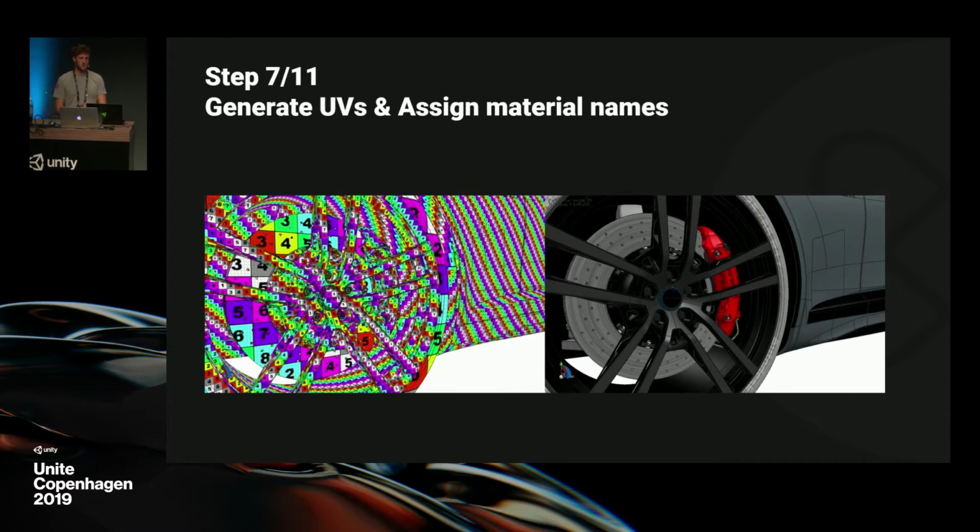Then, thanks to the part naming convention, we use scripting to automatically apply different UV values according to the part typology. And of course, some parts require some specific UVs, like the tires, the brakes, the screens, or the steering wheel. And for that, we can use custom UV matrices.